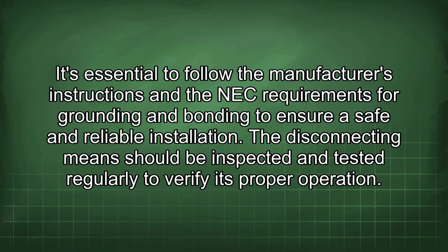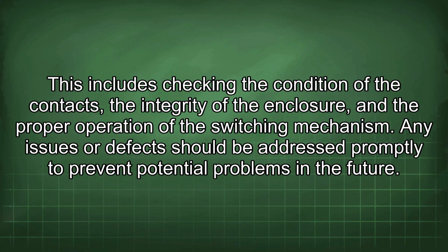The disconnecting means should be inspected and tested regularly to verify its proper operation. This includes checking the condition of the contacts, the integrity of the enclosure, and the proper operation of the switching mechanism. Any issues or defects should be addressed promptly to prevent potential problems in the future.